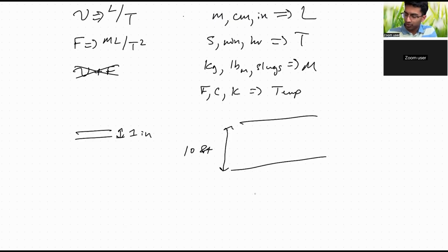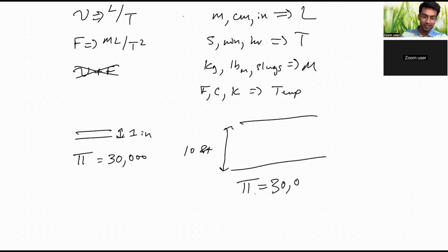However, suppose I told you that there was a dimensionless number associated with this pipe, and that was equal to, I don't know, 30,000. That's just a number I make up. I like that number. Since it has no dimensions, it shouldn't matter how big or small the system is, which means that our larger system should also have that dimensionless number also be 30,000.